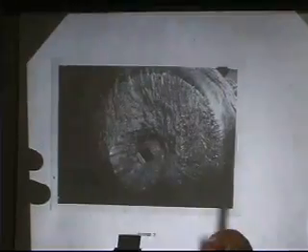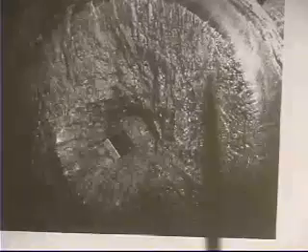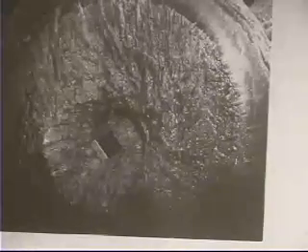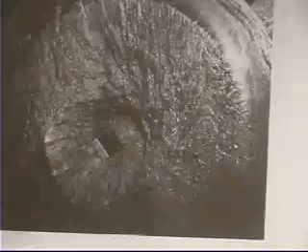Great big forging, 33-inch diameter, has a thermal residual stress crack that was hidden inside, but inside of that, the crack grew from a casting defect from the ingot that was the size of a football. That's a pack of cigarettes sitting inside the defect. That's the initial defect from the steel mill. And the heat treating shop, they grew that little defect into something that went all the way across there. The final solid structure was the smooth stuff, which grew as a fatigue crack. So this whole story brings in residual stresses, thermal stresses, it brings in defects.